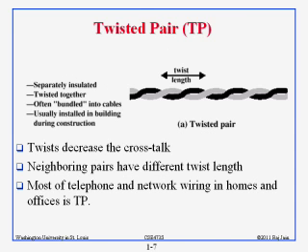So now we are going to send the signal through the twisted pair. The question is, why do we twist? Basically, if you put two wires next to each other, they are both going to be the antennas. They are going to be antennas which are going to transmit, anybody can listen. But that's what the antennas are all, basically they are a simple piece of wire. Right? And when the electricity goes through the simple piece of wire, it just radiates into the air, and therefore it starts affecting every other signal.